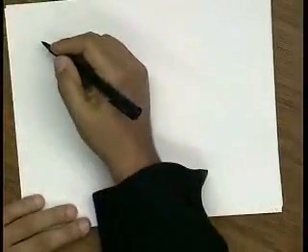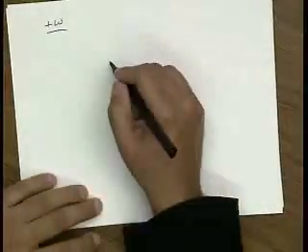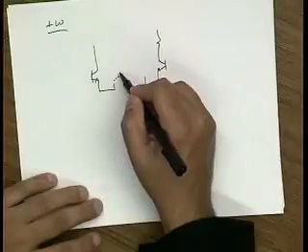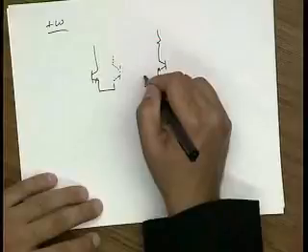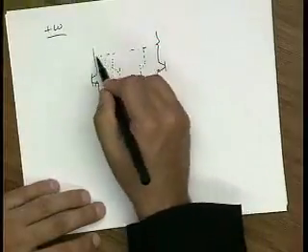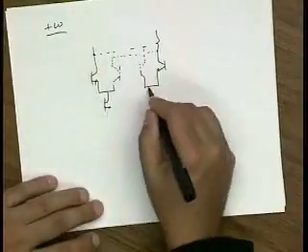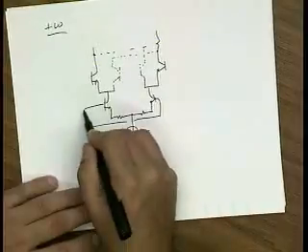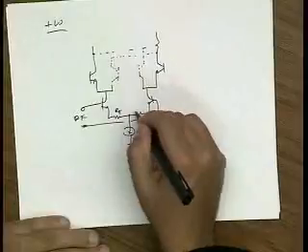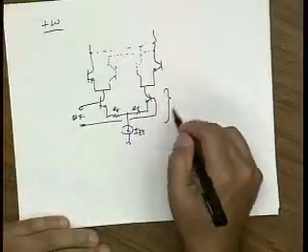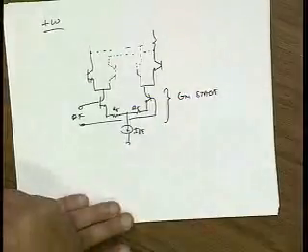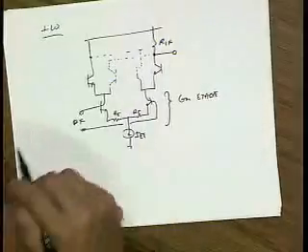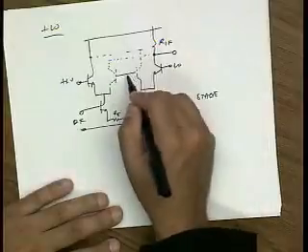So let's draw the signal for different RF. Let's go for a plus LO. So for a plus LO, the two outer transistors are on, and these devices are off. Okay. And this is our diff pair. Now notice this first diff pair, I've put emitter degeneration on there to linearize it. This first pair is just a GM stage, just like before. It's a differential GM stage. So this is the IF port here. This is the output. And this is the plus LO, and this is the plus LO. And this is the minus LO.